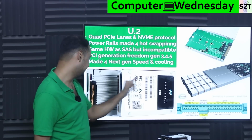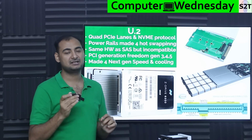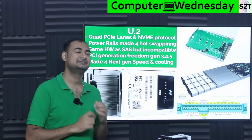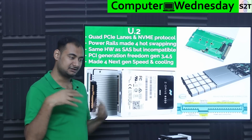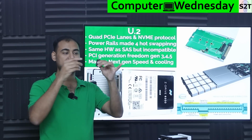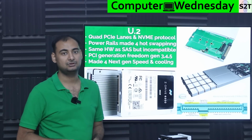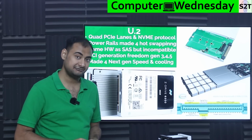It's staggered, meaning the power rail, whenever you see a power rail, is supposed to be designed the way grounds are connected before anything else. Before energization, ground should be safely connected. So ground pins are generally the tallest, and it's done in such a way that both the male and female connectors make contact so that ground will make contact first, then 5 volt, 12 volt and 3.3 volt will be connected. That's the only way to do it safely.